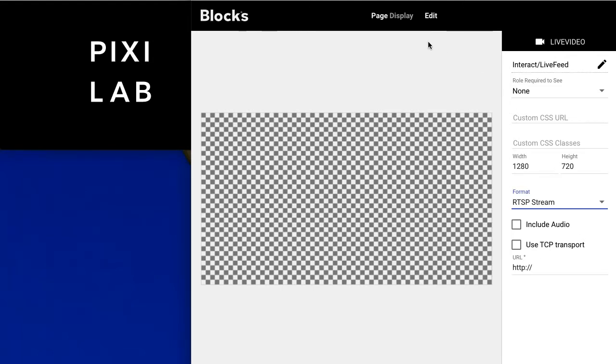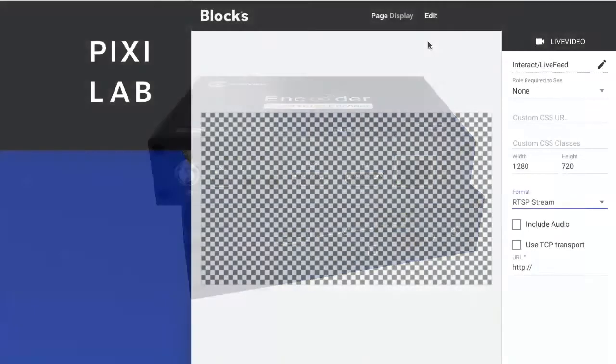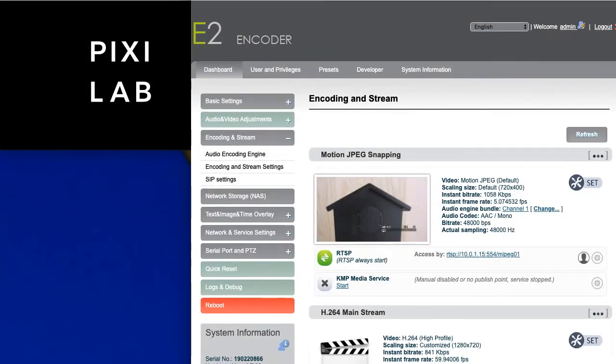In this case, I'm using another capture device. This one is from a brand named KiloView, and they have a couple of different models. This one is taking an HDMI and outputting it onto the network. There you have another similar device that takes in SDI instead, and they have a pass-through and they have a separate audio input so you can take audio either from the HDMI connector, or you can take audio from a 3.5mm analog jack. And this is the settings for that device, the E2.